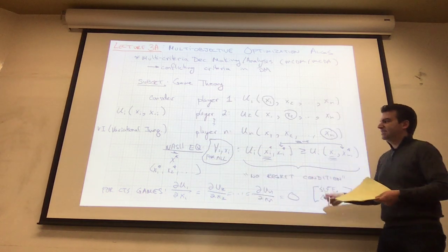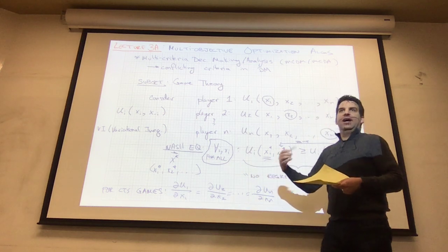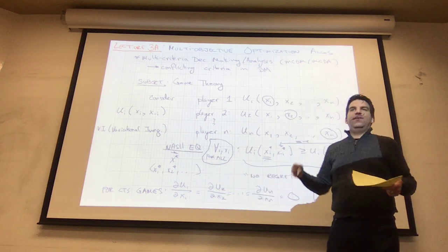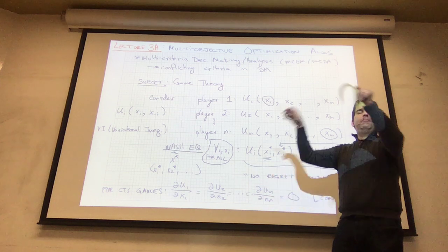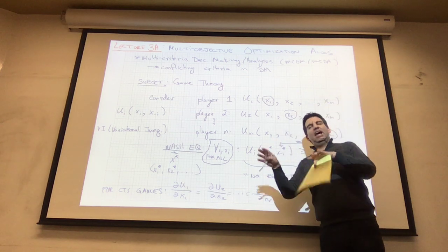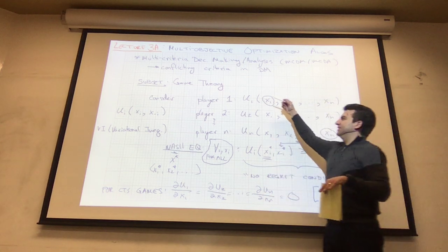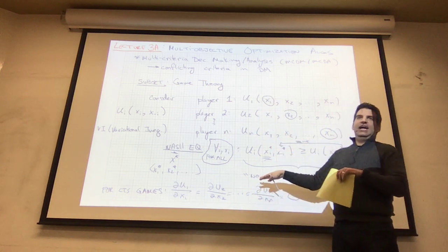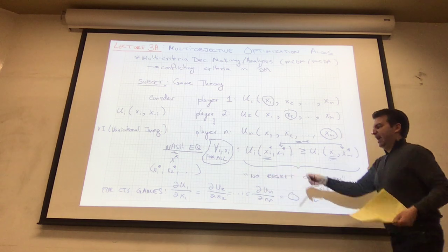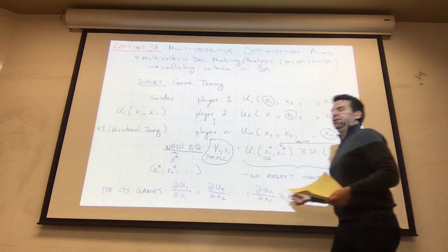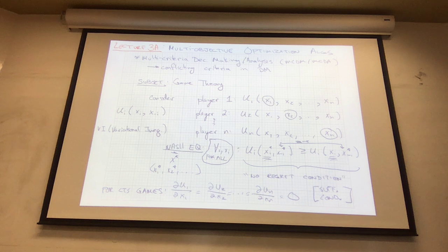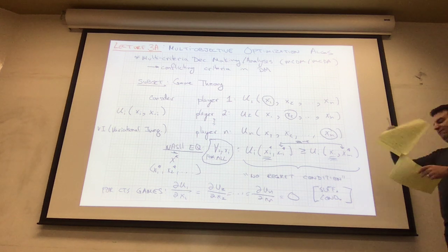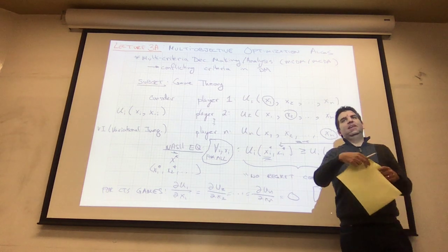And it kind of makes sense that if you've got a robot following a gradient and a bunch of other robots following a gradient and all of their rewards are coupled together, then if you have the right structure of these different utility functions, more often than not, they're all going to settle out at the Nash equilibrium. And that will be where all of their gradients are mutually equal to 0. So this is one equilibrium concept in multi-objective optimization. So any questions about that? The definition here of the Nash.